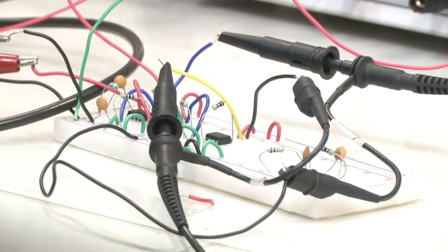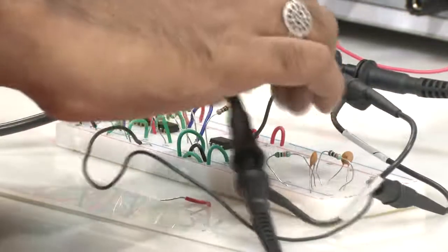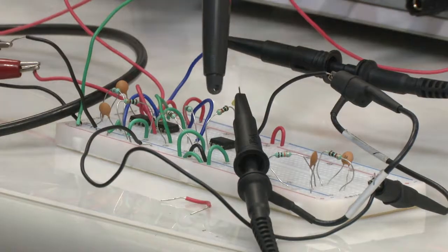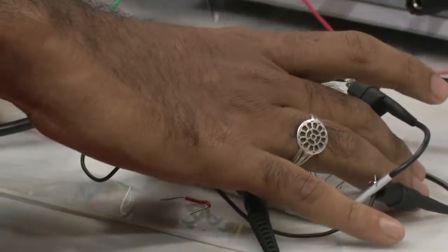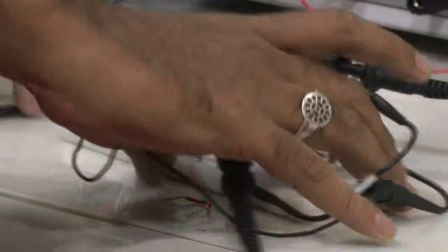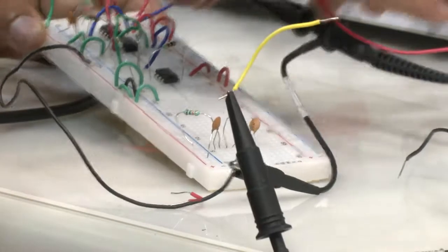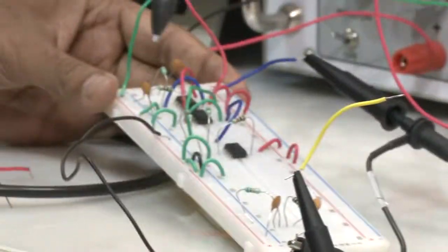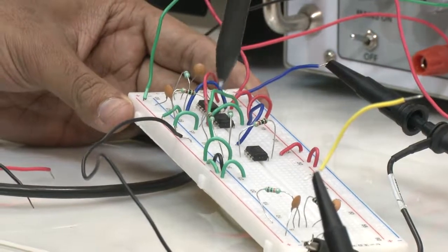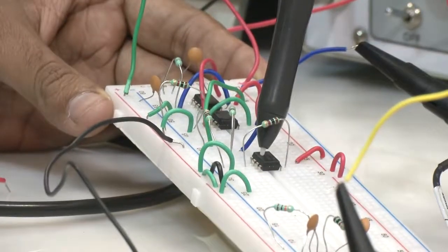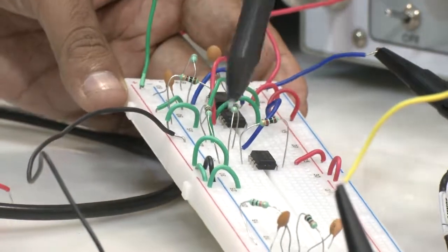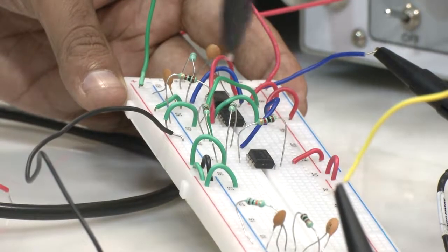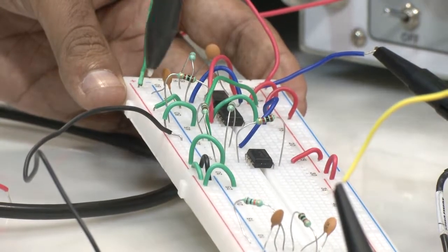we will first see the band reject filter, which is right over here, and you can see that there are 3 op amps. So, now we have here 3 operational amplifiers, 1, 2 and 3, because in our circuit also we had 3 op amps. One is the summer, which is this one, and then there is a buffer, and then the input is low pass and high pass,